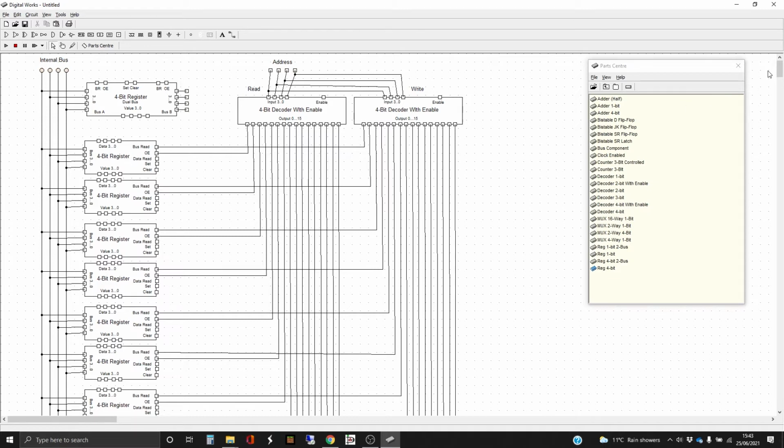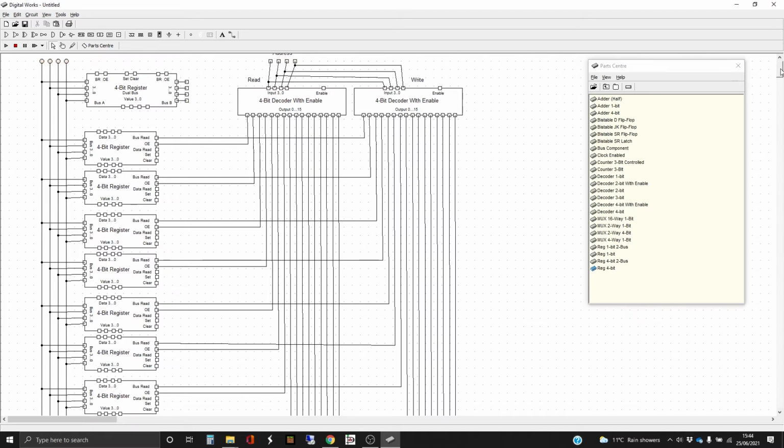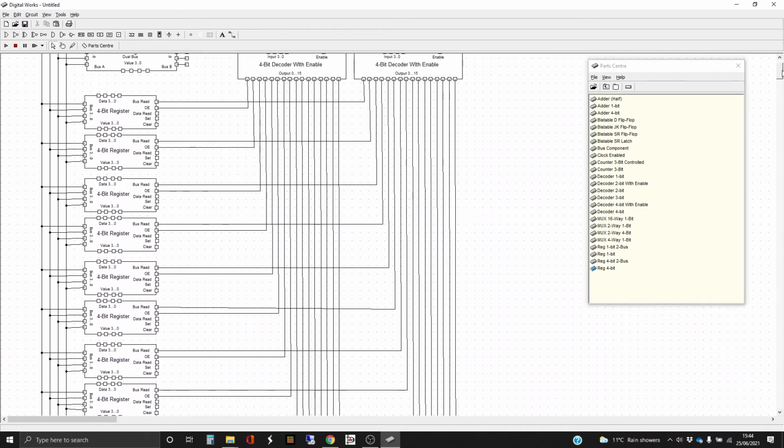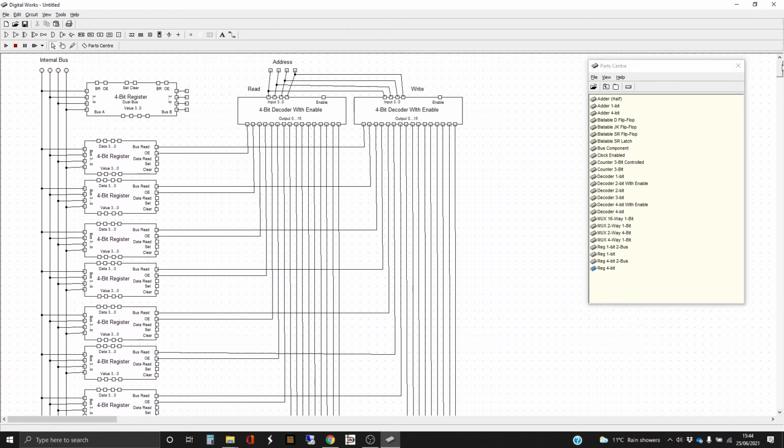For example, you might have noticed a couple of things as I wired this lot up. The first is that I used a little bit of a trick by putting some tags, dragging them down to the bottom, and then connecting across, and then deleting the tags, which leaves behind the wires with the corners. The second one is that the spacing for these outputs on the decoder could have been better in that these lines aren't exactly vertical, and because of that, as I was connecting them, sometimes they kind of disappear from view for a little bit.